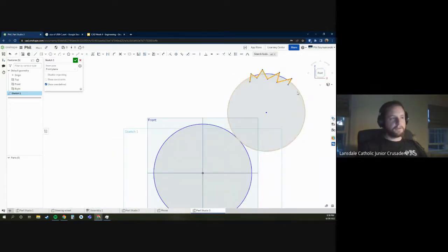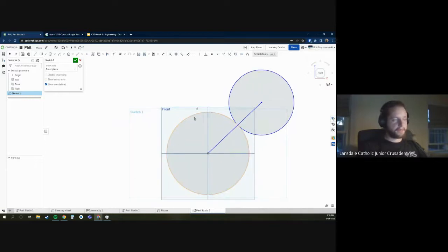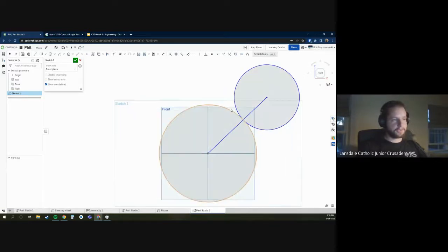So when figuring out the distance from the center of one gear to the center of another gear, it's very critical. How that works is you just draw two circles like this that are tangent with each other. These circles only contact at one point, and that's exactly where this line goes through as well.